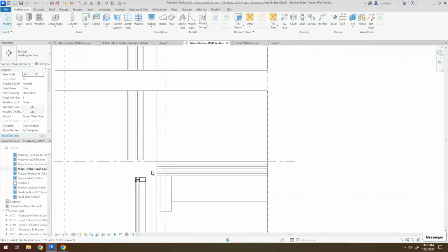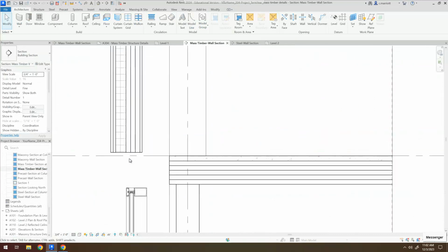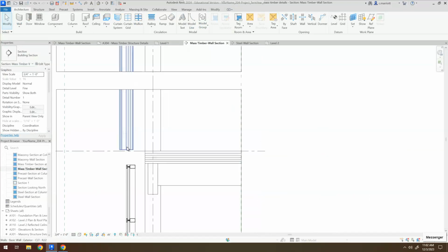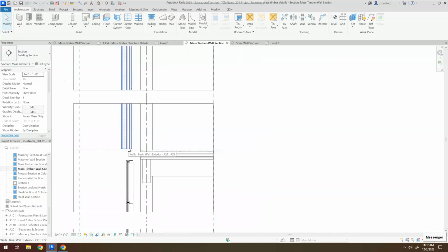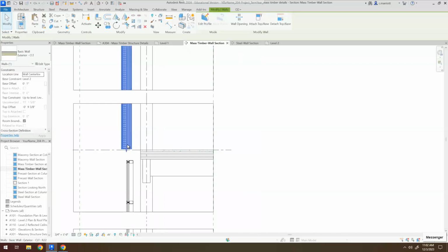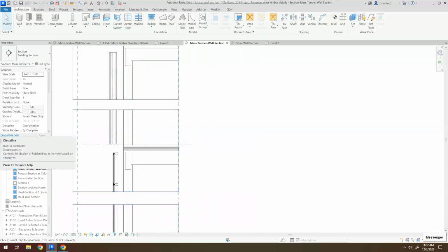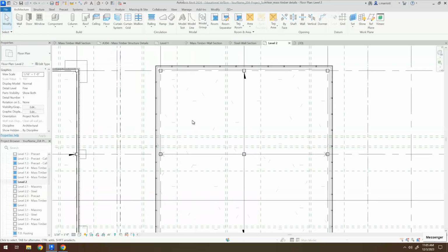Okay. Now, here's where you're going to need to probably make some adjustments. I can do this singularly, but basically we need to make some adjustments to the location of the base offset and the top offset. So I actually think it will be easier, instead of editing everything that's been placed in there, to reconstruct the walls with the proper offsets and everything. So I just erased them. You might be able to Control Z to bring it back to where the walls weren't there yet.